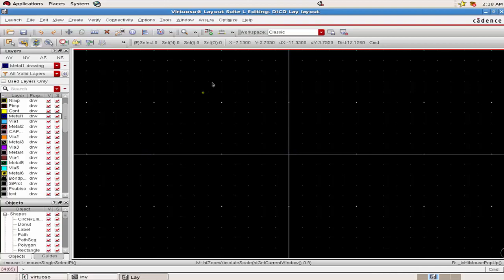As shown in this layout editor, you can see two white lines intersecting at a particular point, and we call this intersection point the origin. Also, you can note that there are dots, a few bigger and a few smaller. The bigger dots are spaced by the major spacing spec, and the smaller dots are spaced by the minor spacing specifications. So we can make use of these dots to our advantage in constructing the layout.